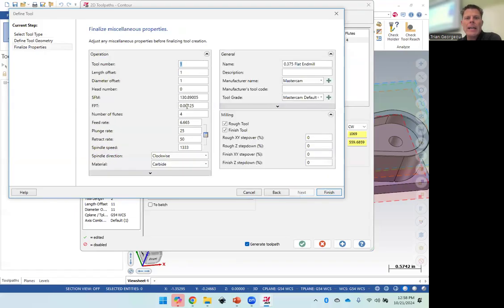And when I go to next, it's tool 12. Its surface speed, I think I put 750. Is that right? Yep. 750, which gives me 7,600 RPM. It's got 3 flutes or 3 teeth. And the chip load was at 3 thou or 2 thou? 2 thou chip load. I'm going real light just in case it's your first CAM. So what does Treon do when he sees 45.8? 46. This far in a minute is not going to break your tool. So 10 inches in a minute probably won't. Well, in aluminum it won't. So plunge, I'm going to just do 24. I like even numbers. You'll see that.